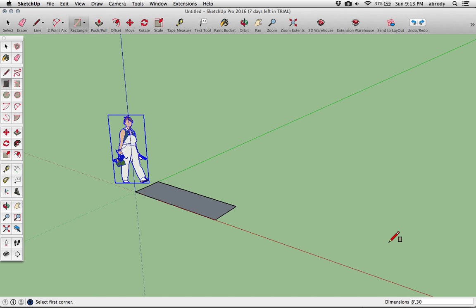And of course, if I want, I can change my mind to 6 feet, comma, 6 feet. Hit enter. I could even type 8 feet, comma, let's see, 30 inches. And then if I decide that I want it to be 12 feet and 30 inches, I can just type in 12 feet and comma and hit enter, and it will change the size of the rectangle just that one dimension. Anyway, I think I like the 8 feet, comma, 30 inches the best.